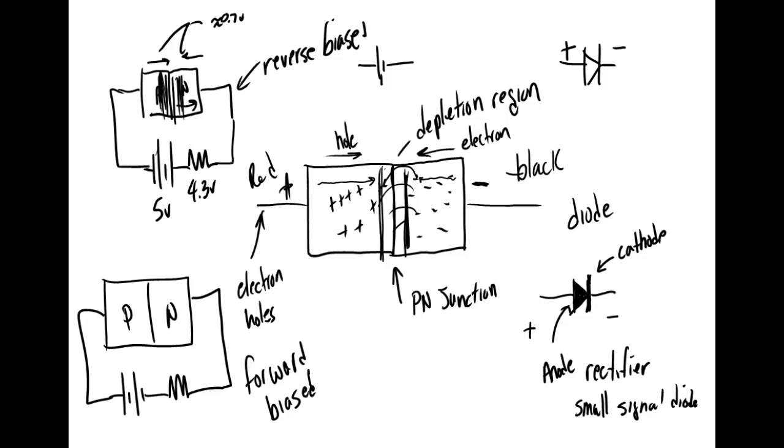We got 60 cycles and 50 cycles. Over here we're predominantly 60 cycles, which is not an extremely high frequency. Rectifier diodes are not designed to switch extremely fast. They're designed to take AC and convert it to DC. So they're more concerned with giving you a current, right? A pretty good deal of current.